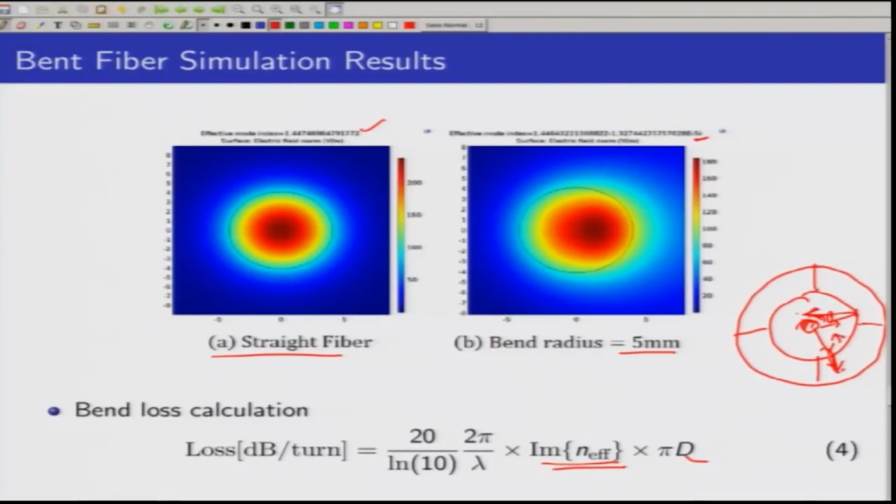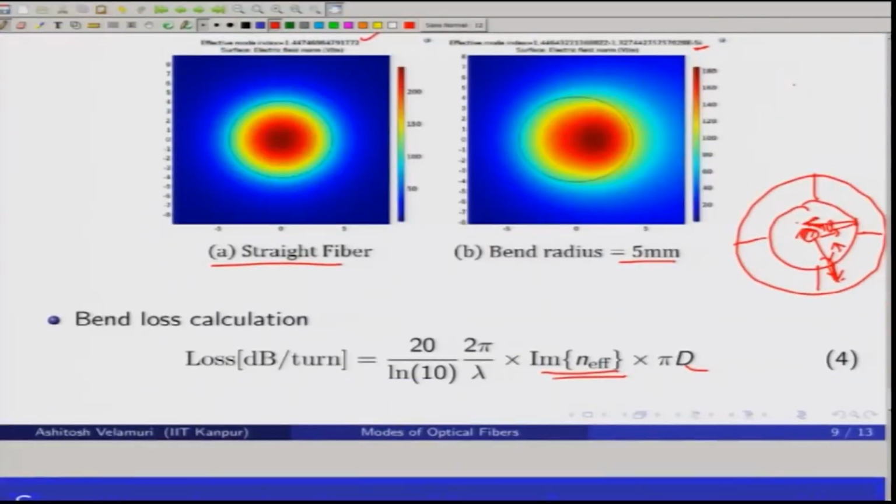So, we are removing unwanted radiation that would reflect back and distort our final output, protecting our results. The imaginary part we obtain here is after applying the PML layer, whose thickness is generally 5 lambda to 7 lambda, where lambda is the operating wavelength.